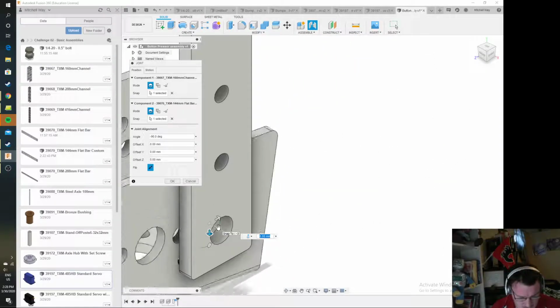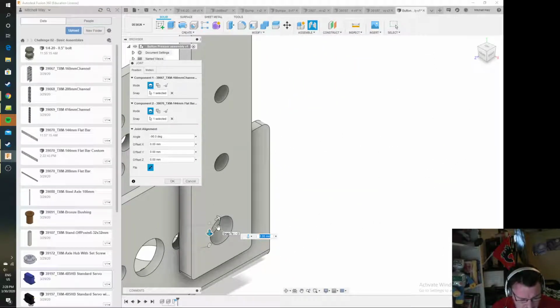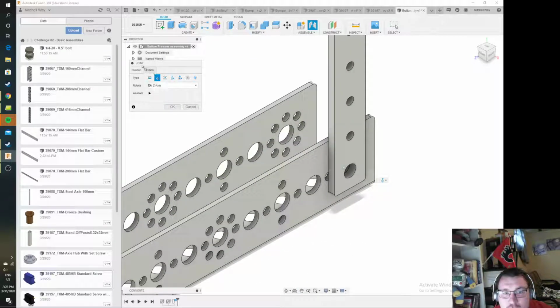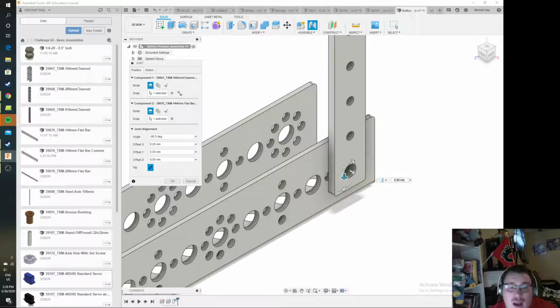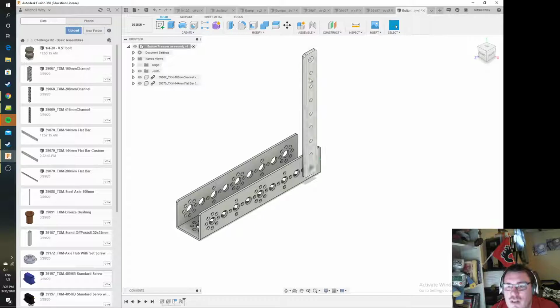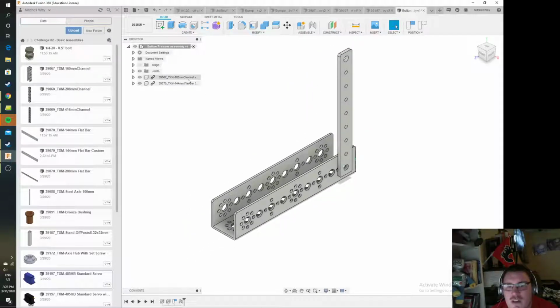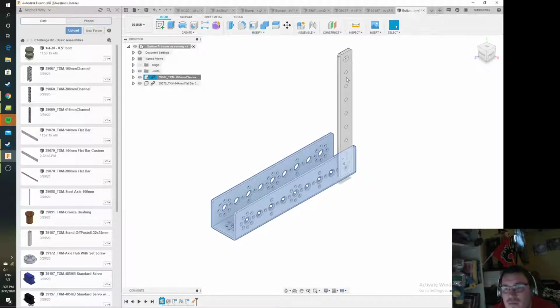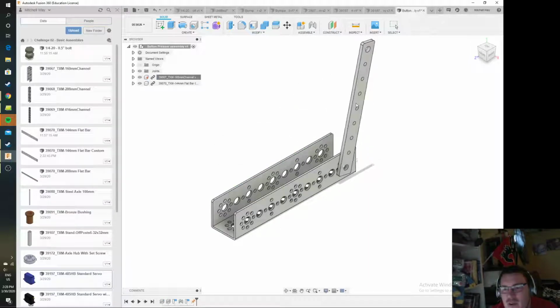And you're going to see some weird spinning going on here. That's fine. Okay, now, the last thing I typed in was a revolute joint, so it is going to do a revolution. I'm going to select these things. I don't need to offset this because of the places I chose, and again, when I move this, nothing happens. That's because I have not grounded my channel. Let's ground our channel, and then we see that once we ground that, we do get the rotation that we want.